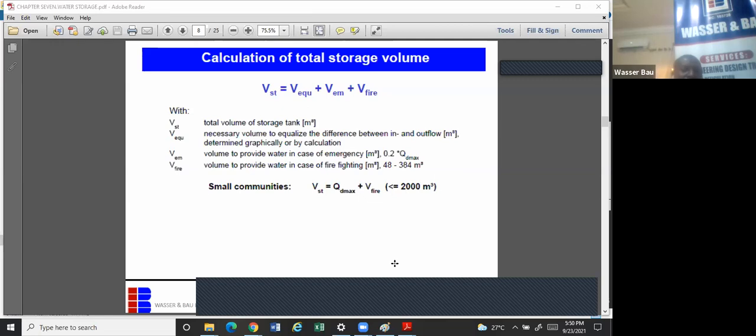We do the same thing in reinforcement design, in concrete design. If you are doing cover for reinforcement, you do it for either 2 hours, 3 hours, or 4 hours, to determine how many hours this concrete or structure can sustain itself against fire before external help comes.